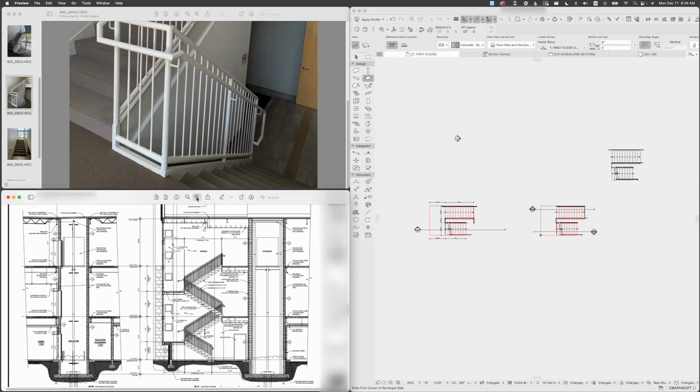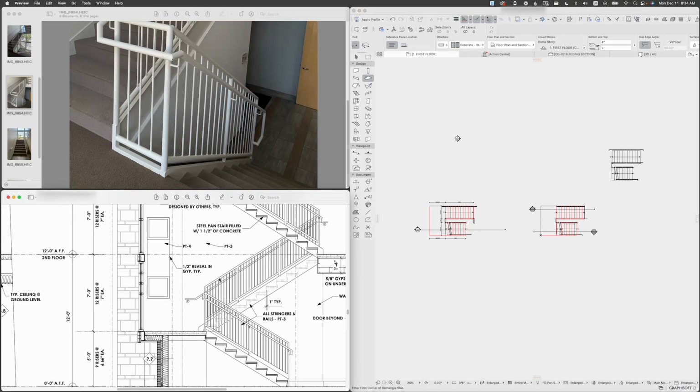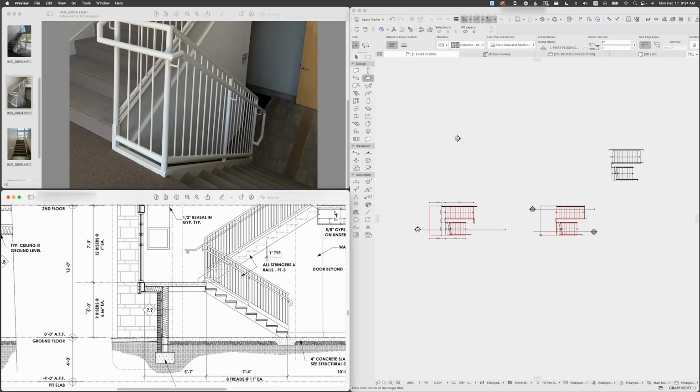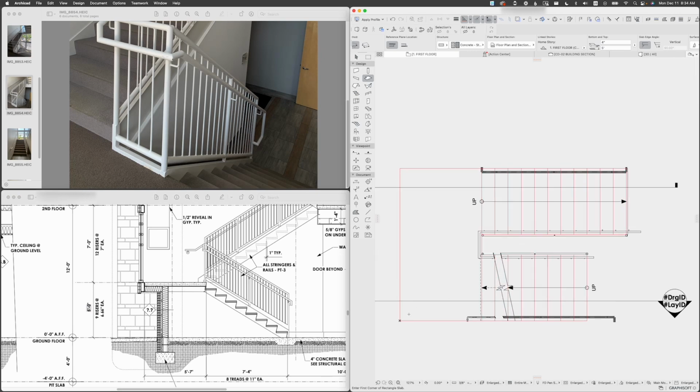Remember, if we look at this section here, right, we have 5 feet high in here, so that's my height. And I would enter first corner of rectangular slab, and I'm using this particular geometry method, the rectangular, and then finally close it up here.